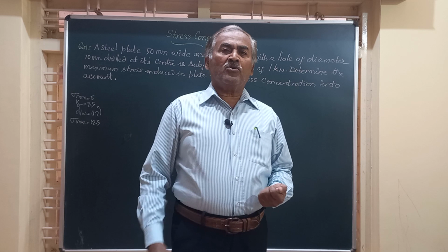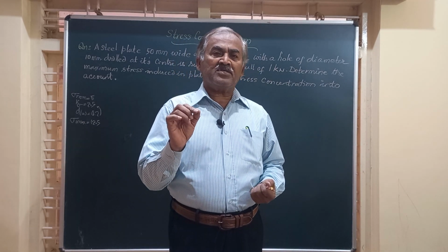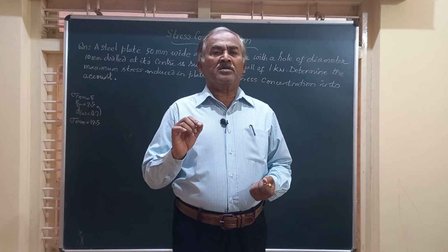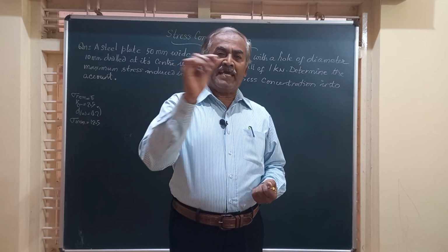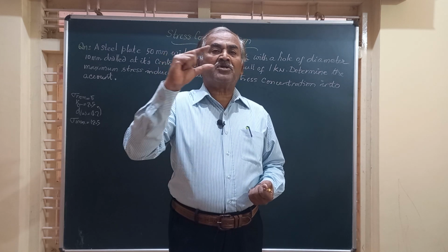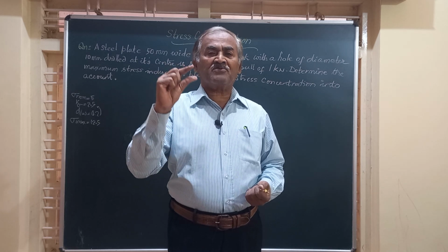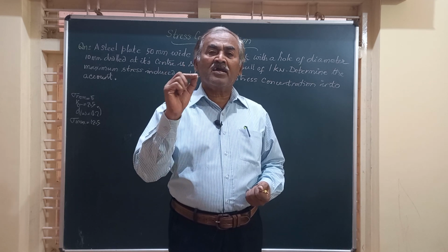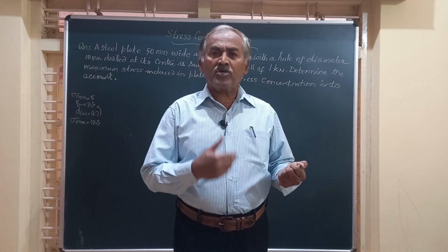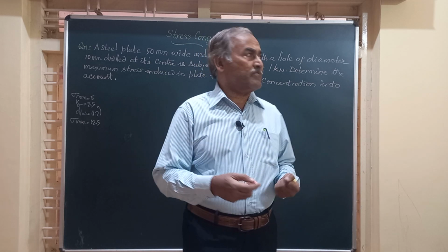Friends, you know, stress concentration is defined as the accumulation of stress at a discontinuity. It could be a hole, a notch, or sudden change of cross section from a bigger dimension to a smaller dimension. So all this will lead to the accumulation of stress and result in early failure of the component. Now let us work out a problem on a flat plate which is subjected to a pull.